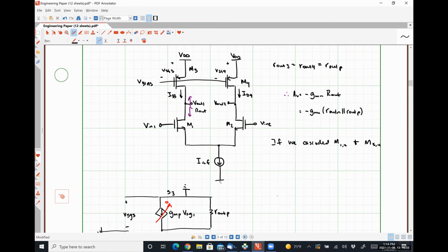So this NMOS on bottom, PMOS on top scheme does a pretty good job of getting us higher voltage gain and a good amount of headroom. The biggest drawback of it is that we still have a differential mode output.